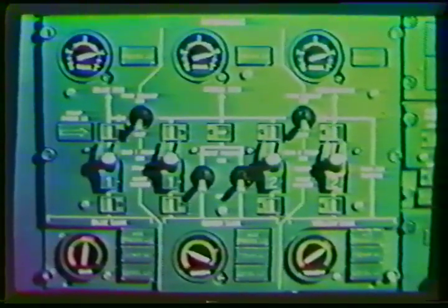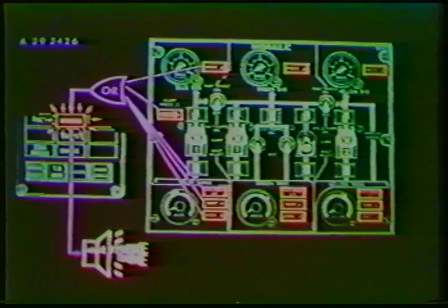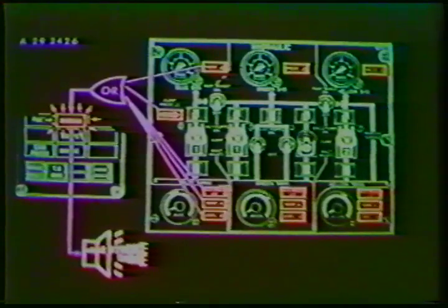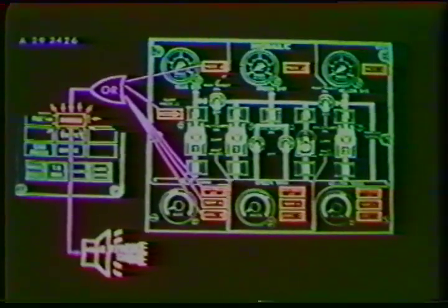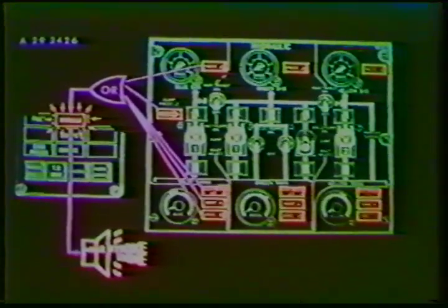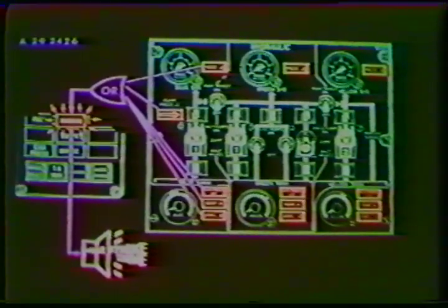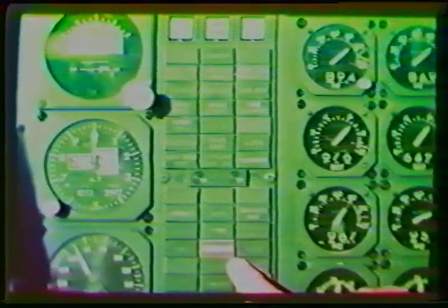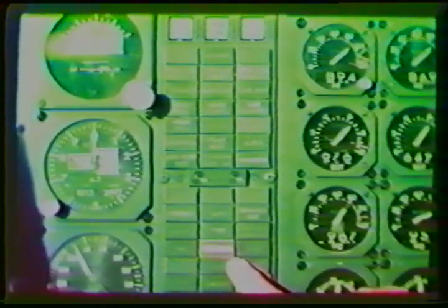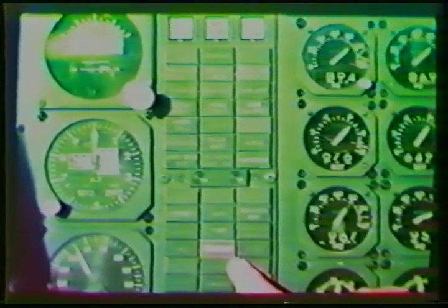The warning circuits with amber warning lights on the hydraulic control module are integrated with a visual and an oral warning of the master warning system. The illustration locates amber lights of the warning circuits which are interfaced with the master warning system. When a warning circuit is triggered, both the related amber light on the control module and the amber hydraulic light on the master warning panel will illuminate. Simultaneously, a single stroke chime will sound.